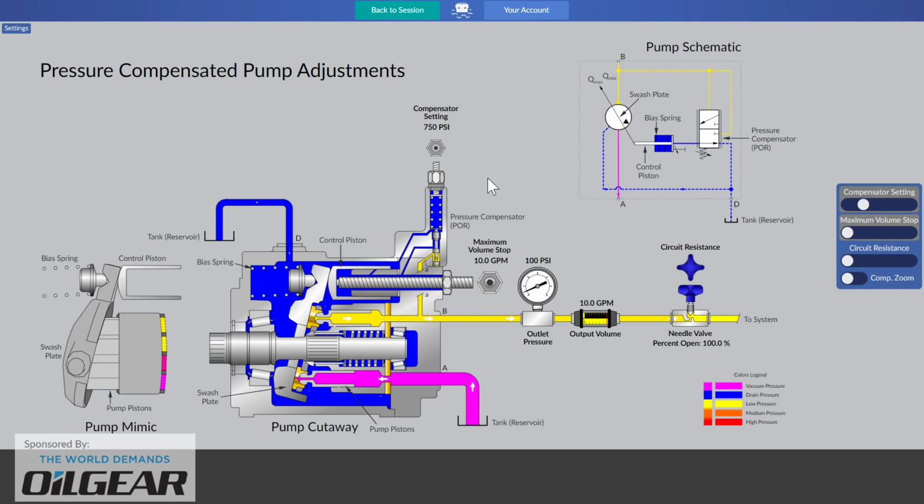As you know, anytime you make an adjustment to a pressure control in a hydraulic system, a pressure gauge should have followed your every move. And in this case, our outlet pressure didn't change at all. We were not in the right system state for changing the value of the pressure compensator, were we? What state do we need to be in to adjust the pressure compensator? That's right. We need to have our flow out from the outlet of the pump blinded out in order to take that pump into the condition of triggering that pressure compensator.